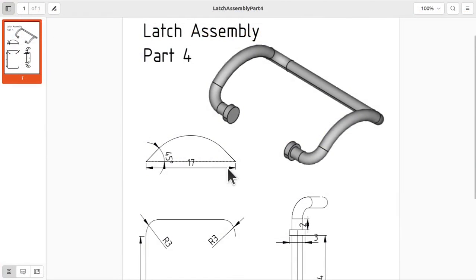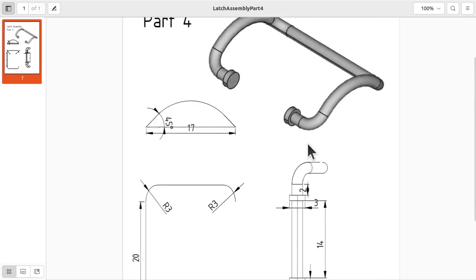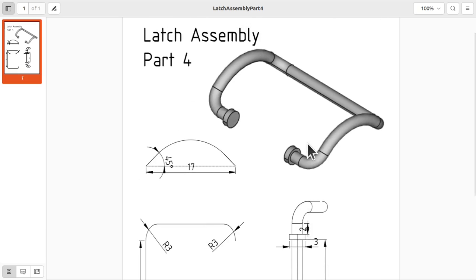We've come to the part of the project where we need to create this feature here. So this is just an extension out of what we've already done with the additive pipe and then this disc. We can see that we've got a 2 millimeter length to add plus a 3 millimeter diameter of disc, which is 1 millimeter in length. We don't have to add a sketch for this. This can be done with a standard pad.